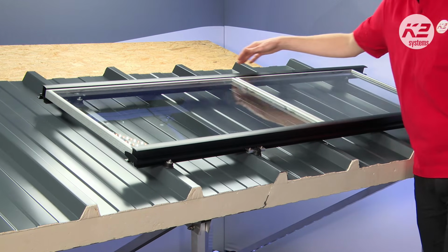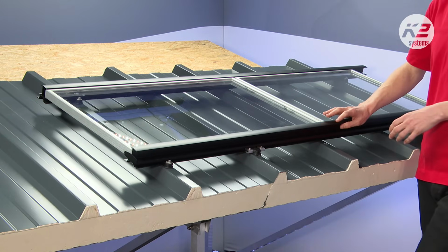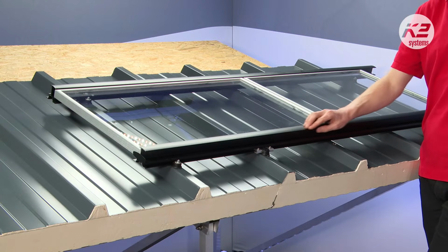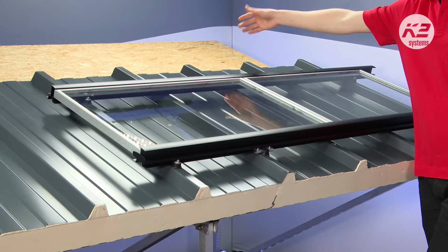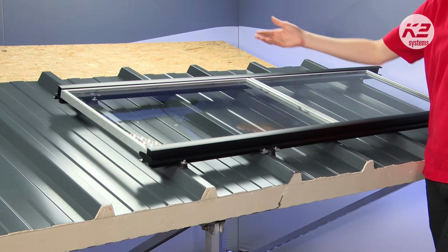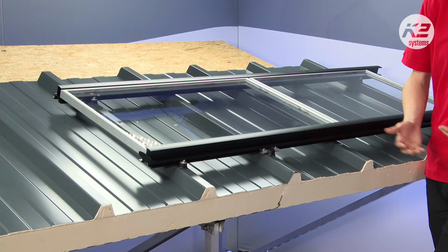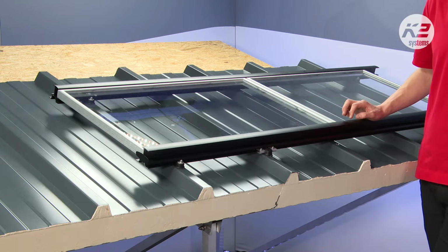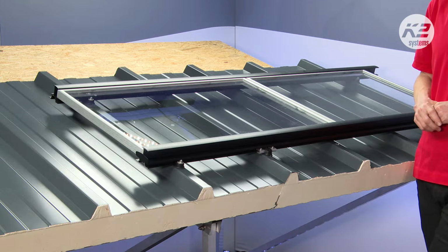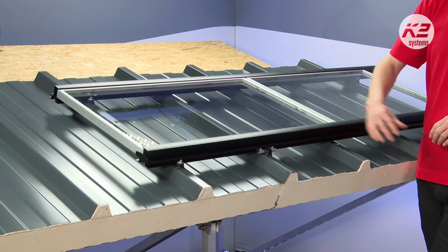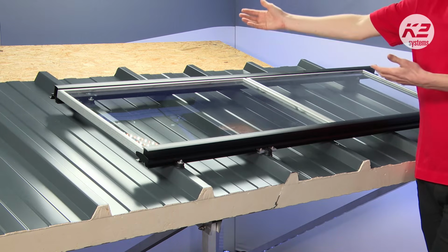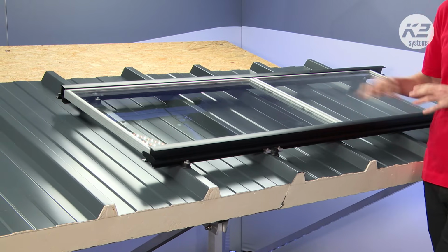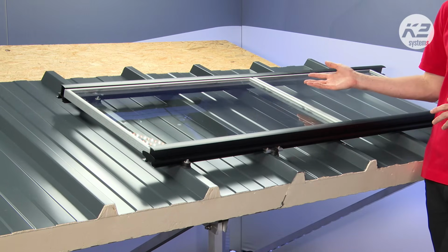And so you have this 1.5 concept where all of the weight is being pushed down onto only one rail, and in the next row, all of that weight is only on this one rail, right? And so every rail is just carrying effectively one panel, which is a pretty clever way of doing it, if you compare it with some of the other systems where, if you were to have a vertical rail running down, the potential weight could transfer down the roof through the panels, through the clamps, into each other's system, or into the system below. But that's not something that will happen here.